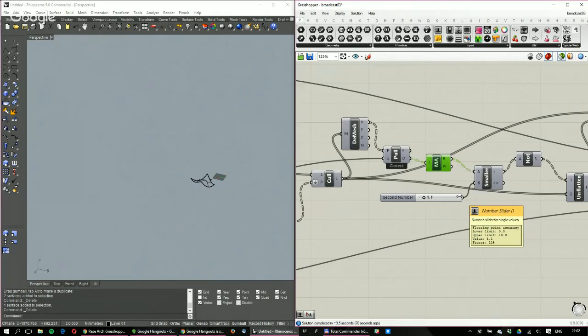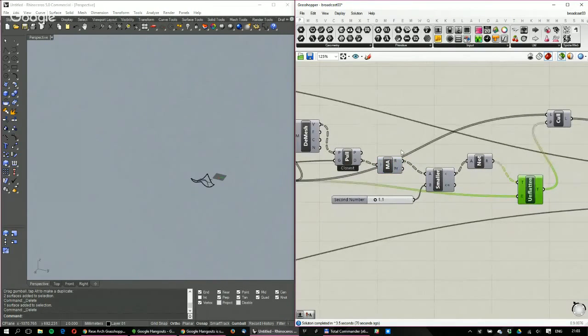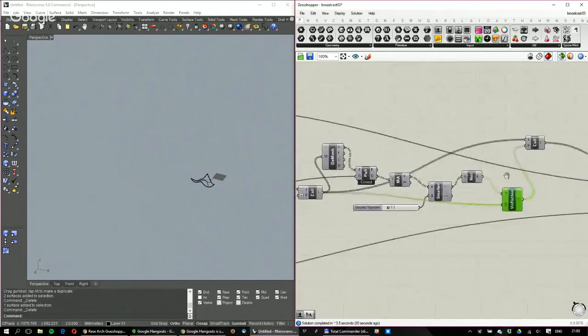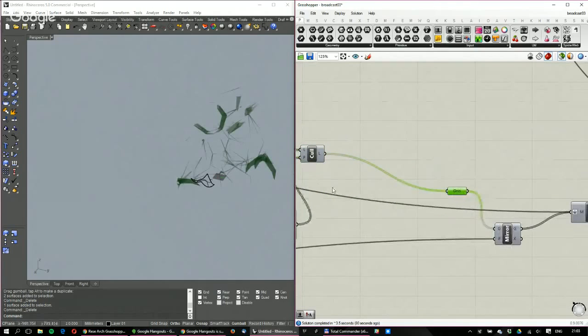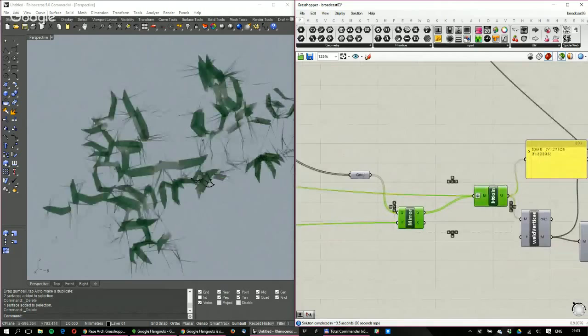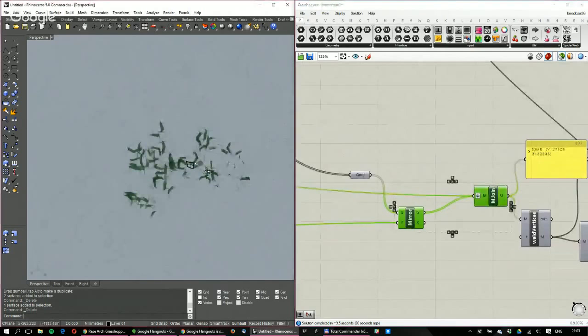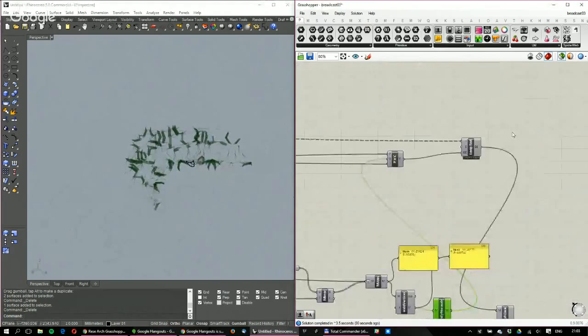It's like mirroring something that is touching the mirror. So I'm just removing everything here that is touching the plane, a cull, and then I know that the remaining part I can mirror, and I jump to the rest of the structure that I have.